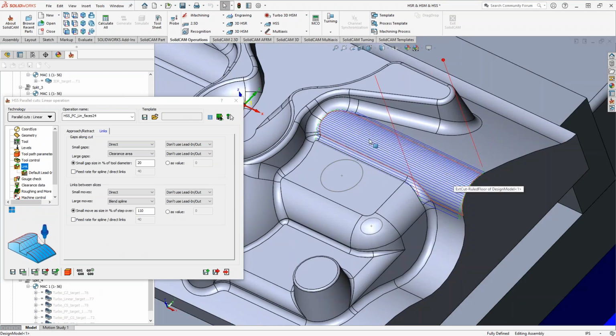So this one here has that nice smoothness there. And then every other toolpath, I would change direction or choose a different technology to follow the flow of the surface. So that blending between surfaces, like Kevin said, is actually really important when you're using HSS.